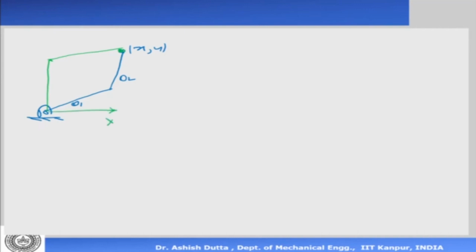This is my x, that's my y. For this value of θ1, θ2, you get xy. But if you have the other value, this is my θ1 dashed, and that is a minus θ2, you get the same xy. And why is this happening? This is happening because sine and cos have two terms. So this shows you that there are two solutions actually, what we call multiple solutions.